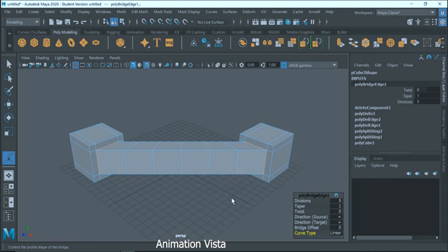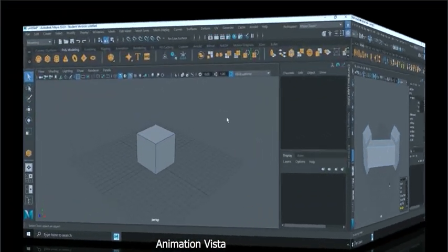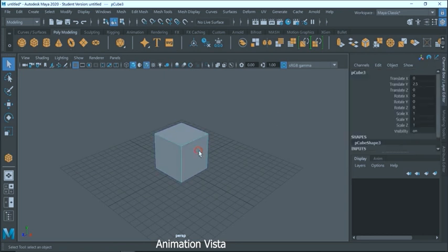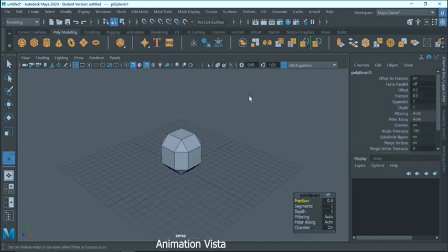Now let us move on to beveling objects. Beveling is the process in which new polygons are created in place of the selected edges on the object. We bevel objects to create smooth corners. You have to understand one thing here, that selecting a face also means technically you are selecting all its edges. Alright? To bevel objects, first we have to select the object if we want to bevel all its corners. And then go to Edit Mesh and click on Bevel.